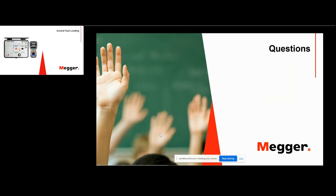So before using anything on that system, it's best to consult with the design engineer and have the recommended maximum current values or voltage values defined. Then you can program them into the transmitter. So yes, this is safe to use on that, but I would recommend that you find out from the engineer what the maximum limits are.